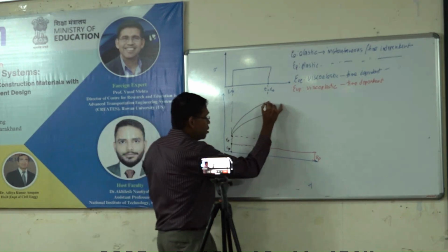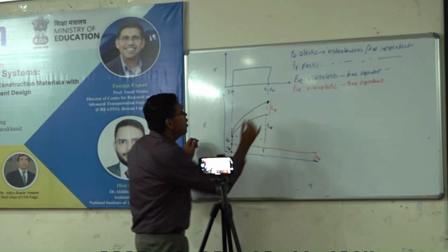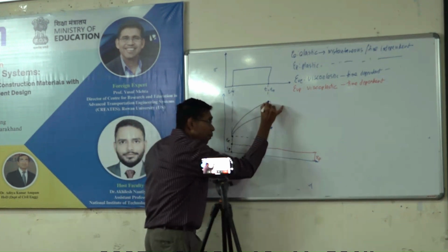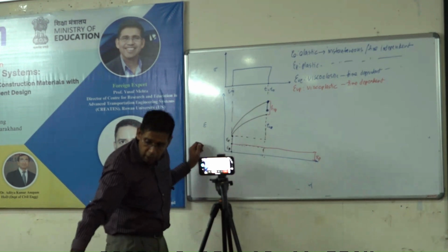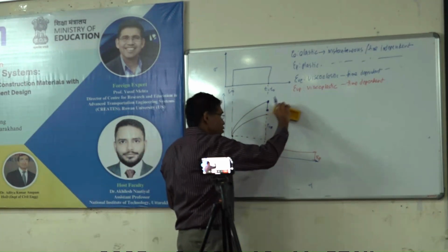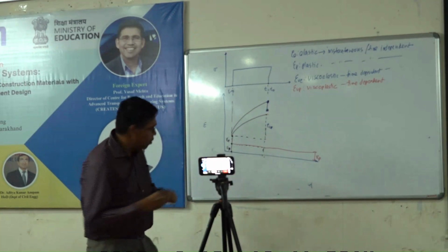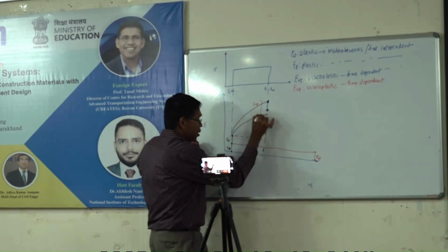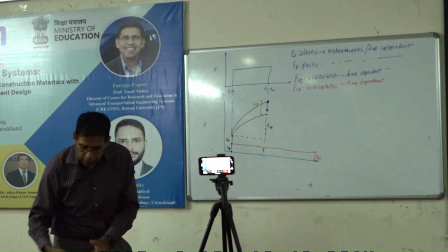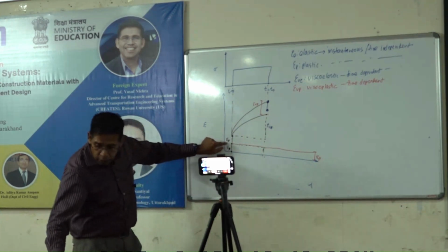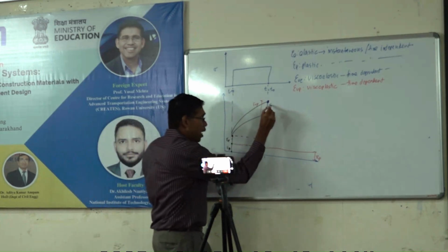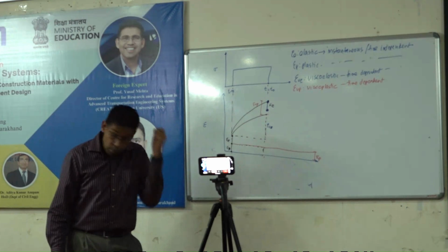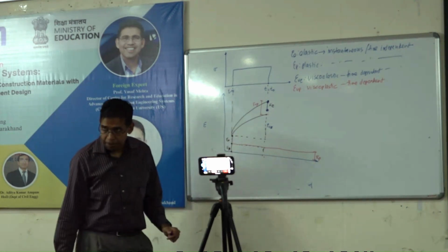Now I'm right here, right? And as soon as I remove the load, the elastic portion, epsilon E, I'll just erase this for a second to make it clearer. So this is epsilon Vp, right? This one. As soon as I remove the load, epsilon E that was there will come down right away. Because it's elastic, time independent: you remove the load, the elastic portion comes back.